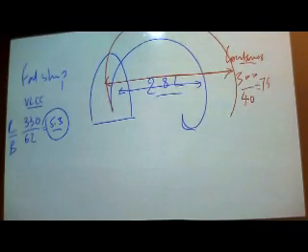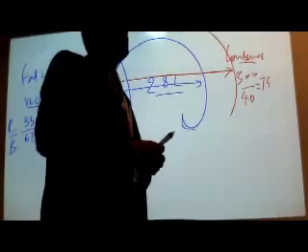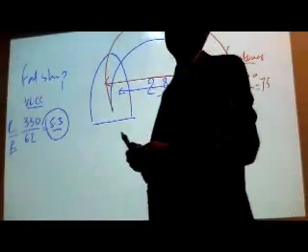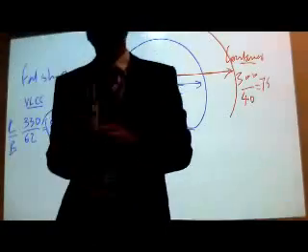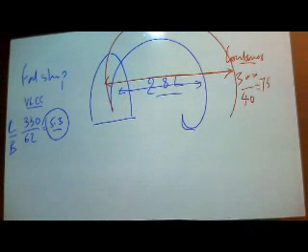What is the normal length of the LNG or LPG that we use? Depends on the amount of volume that it carries. A 200,000 CBM LNG vessel would be somewhere around 350 meters long. 150,000 CBM would be about 270 meters long. Depends on how much you are planning to carry. The more you want to carry, the bigger the ship. The less you want to carry, the smaller the ship.